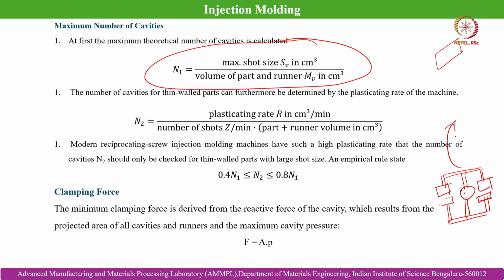Another example can be when it is kept further apart. So, these are the parts which are mounted, and similarly this is the sprue, then this is getting separated, and this is the part mounted. So, this is a typical example of balanced runner design that we can generally follow in case of powder injection molding, be it polymer or metal or ceramic. So, you can see these are actually 1, 2, 3, 4, individual cavities.